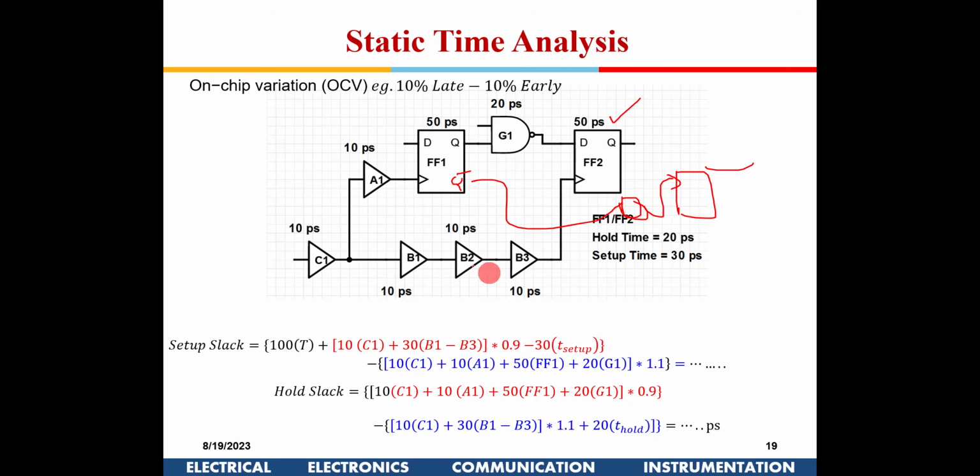Hello, sir. Yeah, and the slack will be... suppose you are doing an analysis. There are different circuits, might be different flip-flops, and different paths will have different slacks. So your max frequency, which you decide finally, has to cater for that worst case path.